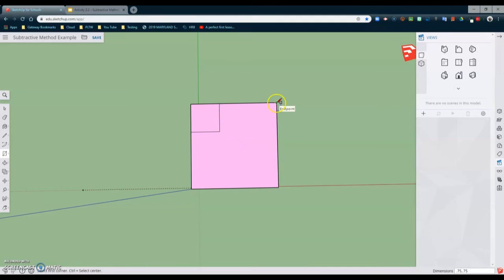We can do the same thing in the upper right hand corner. We're going to drag that rectangle out, add a 0.75, a comma, and then another 0.75 and then enter. Now you have the two squares in the back left and right that we can go ahead and modify.